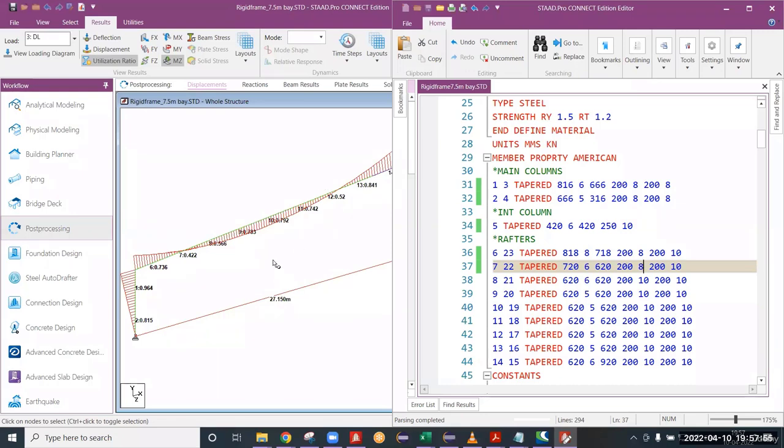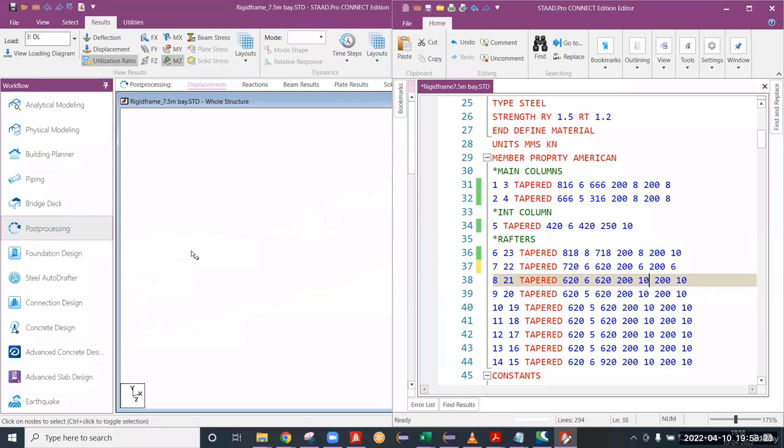But if you see the serviceability condition, the deflection, it will get failed if you reduce the web depth. That is why I'm not advising to reduce the depth here. Instead of that, I'm reducing the thicknesses only, because the thicknesses anyway tend to gain more weight. So I'm reducing the thicknesses. Okay. In this portion also, this value is for 8.